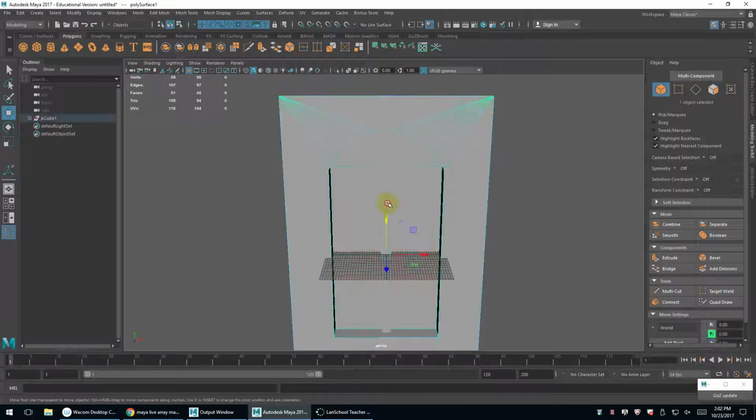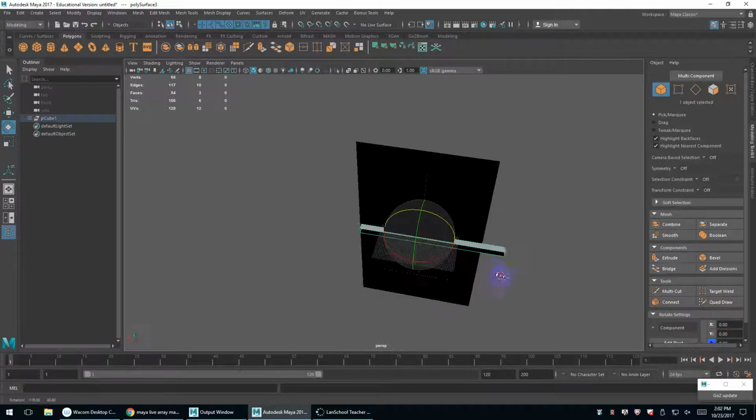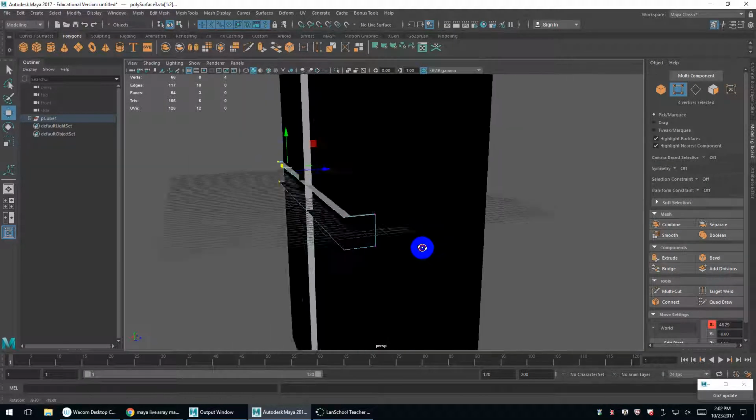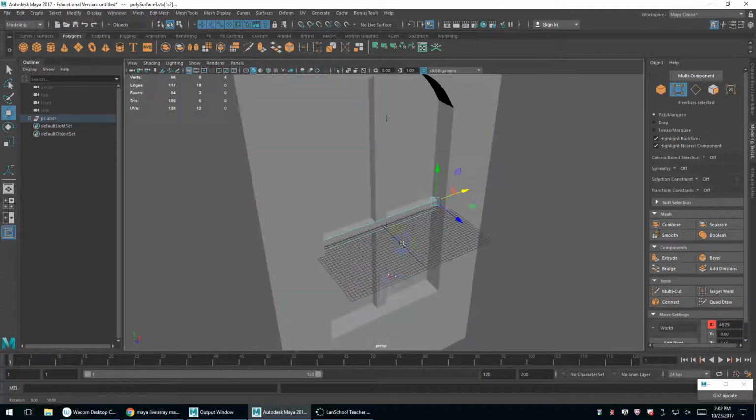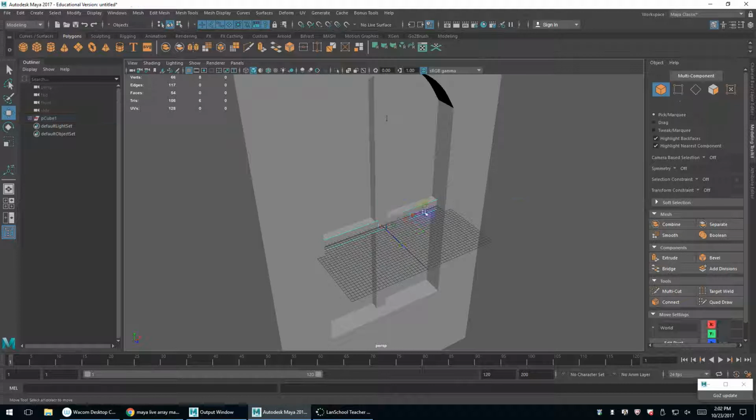Now if I go back to object mode, this thing is still separate. So I'm going to hit Control D. I'll rotate this thing 90 degrees. There we go. Again, I'll take the outer vertices or outer edges. Doesn't really matter what you grab. I just like to bring them in. Again, I'm really trying to make sure I get just enough coverage, but I have no back-facing polys here, right? So think about this. Depending on how many windows you have, this can add so much to the scene in terms of mesh. So let me maybe tuck this down and in a bit.